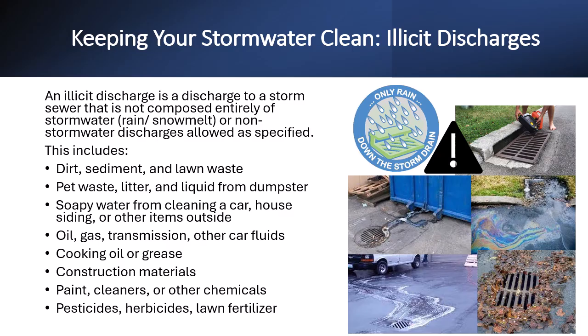One example that often catches people off guard is that dirt, sediment, and grass clippings or other lawn waste that gets transported from a yard into a storm drain is considered an illicit discharge. This is often seen as natural. However, lawn waste, especially in large amounts, can clog our storm sewers, contribute to nutrient and sediment problems, and convey chemical contaminants such as lawn fertilizer and pesticides.